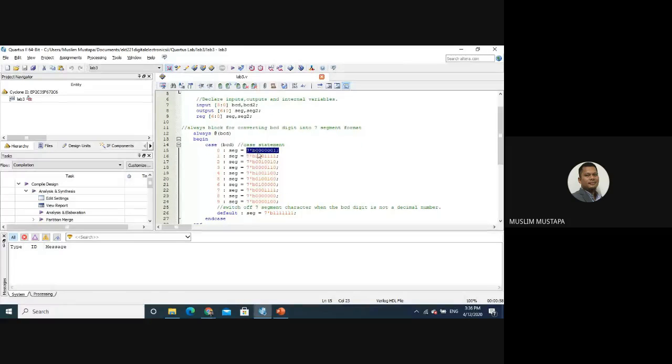This is your control bit, to turn on your LED inside the 7 segment display. As we can see, most of it is zero for zero number because your 7 segment is active low. Active low means that it's going to light up when you are giving the low signal, which means you connect it to the ground. So when you connect it to the ground, you complete the circuit, giving the current a path to flow down to the ground and light up the LED.